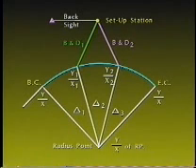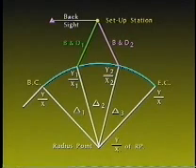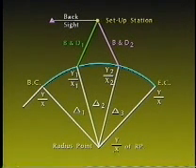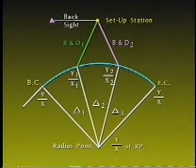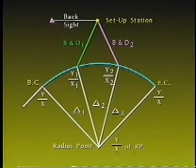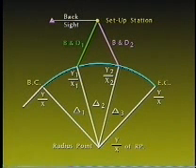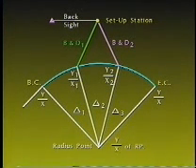Coordinates are calculated for each POC that is to be set to define the curve by using the bearing and radius from the radius point. The bearing of each sub-POC is determined by applying its sub-delta to the bearing of line RP BC. The resulting coordinates of individual POC stations are used to obtain bearings and distances to the POCs from the setup point by the inverse generation process. All calculations should be done in a logical sequence and be neatly tabulated.